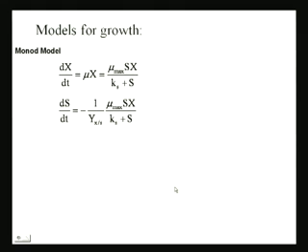Okay. In a similar vein, we can write the growth model, the dS/dt, again for a batch reactor for the substrate. So x is my cell and S is my substrate, and the reaction rate is the same over here, except there is a negative term outside because substrate is being consumed in the reaction, whereas the cells are being generated. And why is this Y x/s? Because we discussed this in the last class. Y is the yield of x per unit mole of S.